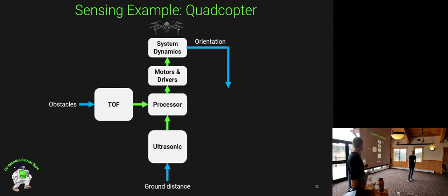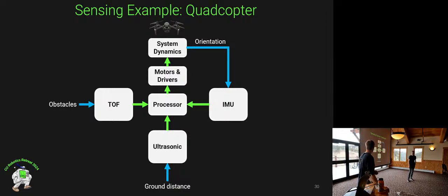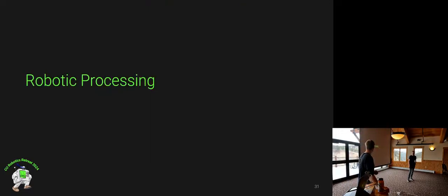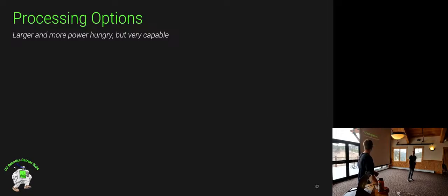Yeah, yeah. So the time of flight sensor. They've used these on Crazyflies, for example, to do fully autonomous navigation. They're super cheap and they're lightweight. You can get them literally this big. Some of them do 8 by 8 or 16 by 16 arrays, so they can do a poor man's kind of depth sensing. And then orientation, I think, is pretty obvious. It's an IMU, right? So having all of these sensors on a system enables you to have some sort of fully autonomous system that can navigate by itself.